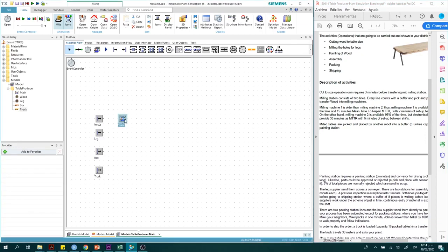So let's say that you're going to have the milling station here, but you can use a station or an operation for the cutting activity. So you can rename it cutting, and this is connected to good. At the end, we're going to connect everything. It is also good advice from simulators that you have everything isolated and then you connect everything. That way, you're going to have order in your simulation.